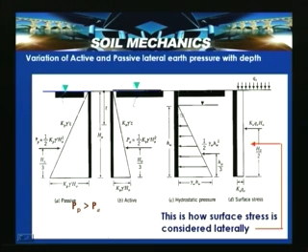this has got an additional component. If the water is there up to this level, then that acts as a hydrostatic pressure, which is half gamma W h naught square. But if the water table is there on both sides, say the wall is submerged, with water on the left hand side and on the right hand side of the wall, then that hydrostatic pressure gets cancelled. Then the effect of water we need to consider by calculating the submerged weight of the soil and the lateral pressure due to the submerged soil mass.